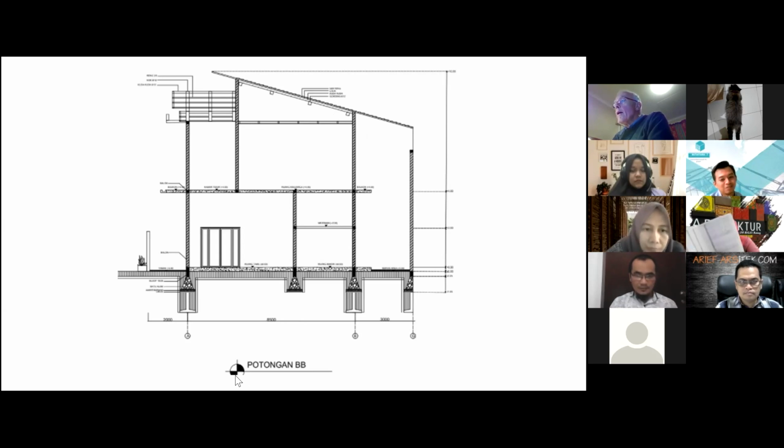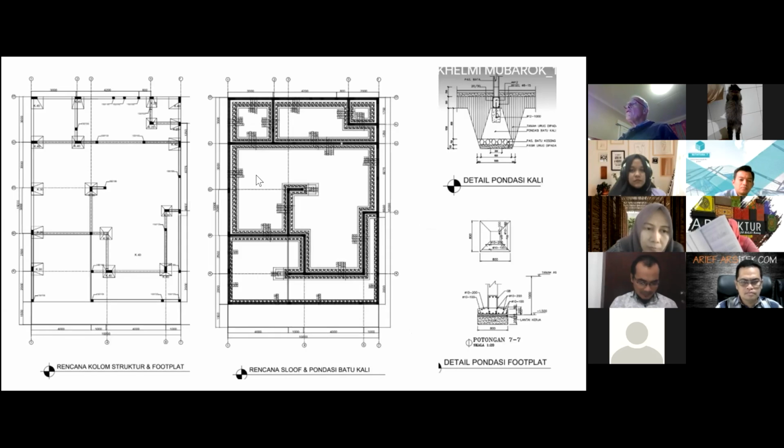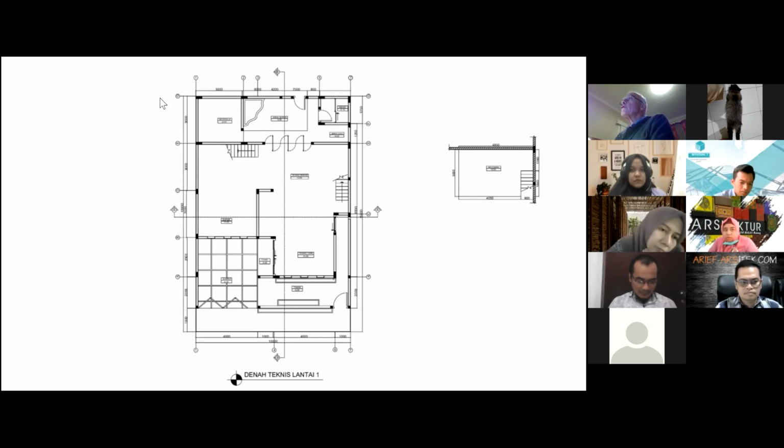So going back to the ground floor plan again. What we've got now is some resistance on grid G, some resistance on grid E, but no resistance down here. And so this means the building has got a severe torsion problem. During an earthquake, the earthquake forces will attack at the center of gravity of the plan, about here. But the resistance from these two grid lines will be about on this point here.